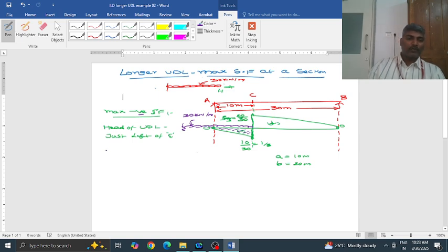Now the shear force value. By previous lectures you have learned that when there is a UDL, the function value is equal to the load value multiplied by the area of the ILD occupied by the UDL. I'll calculate that value. It is a triangle, so half, base is 10 meters, height is the ordinate that we have calculated, that is 1 by 3.